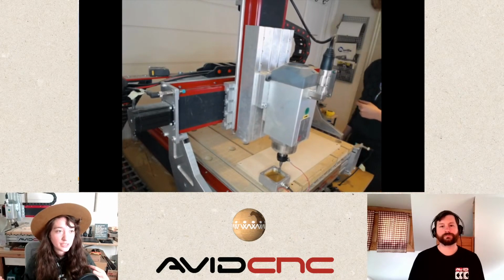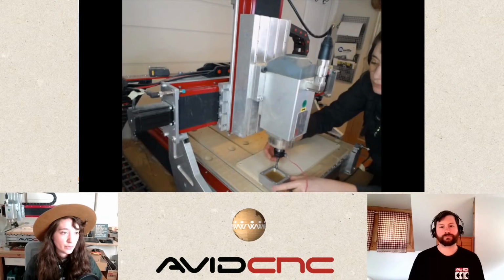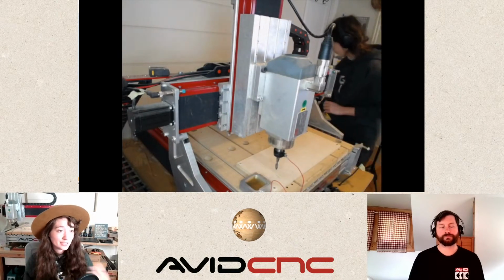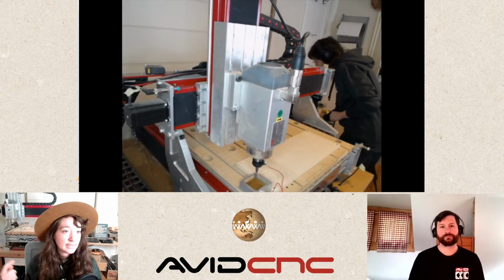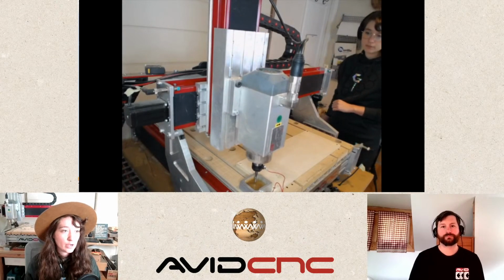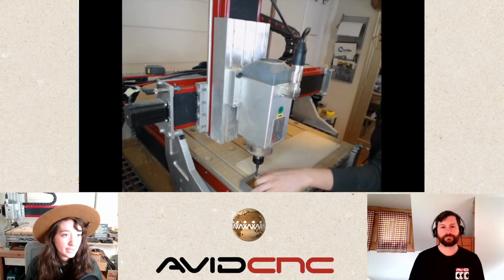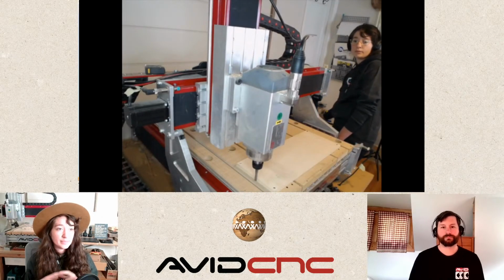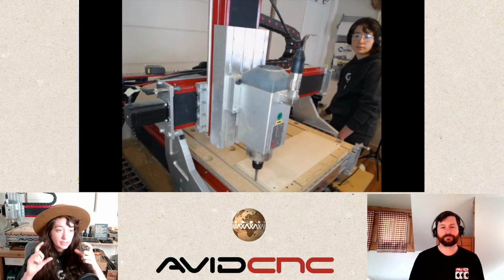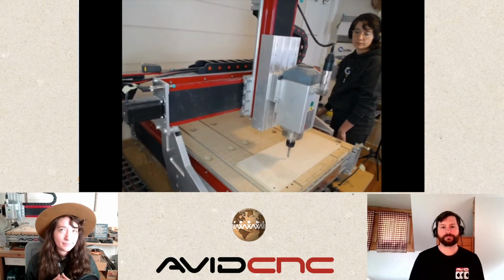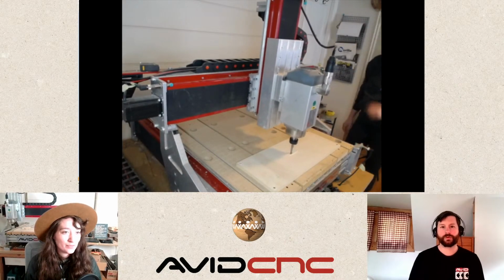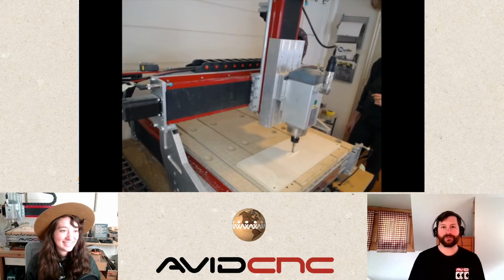So I changed it from what we had as the original 0 setup, but you can just adjust that on the fly as you need to, right? Then I'm setting my Z to the spoil board bed, and I'm going to pocket out the size of the material, the aluminum itself, with some dog bone fillets in the corner.